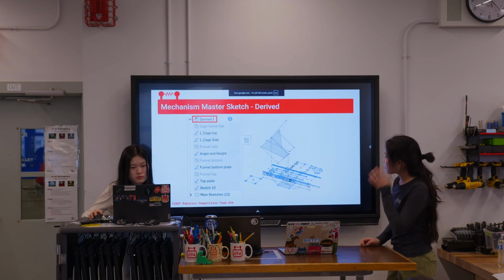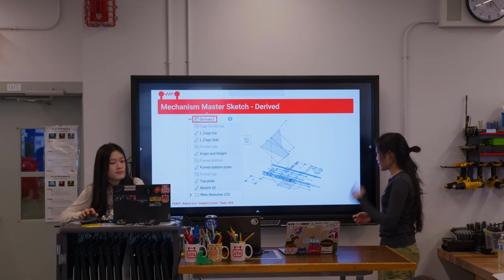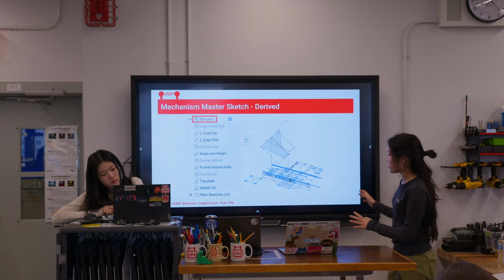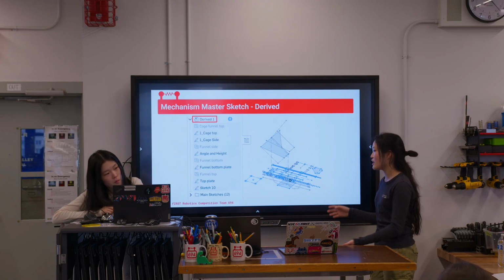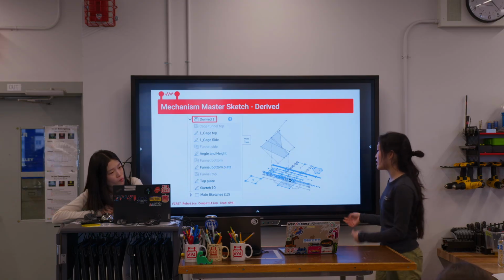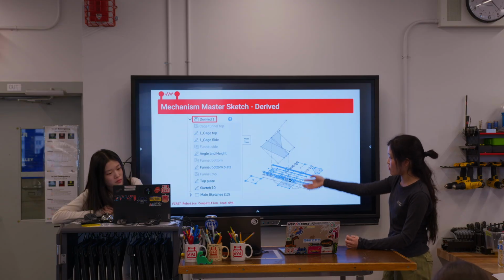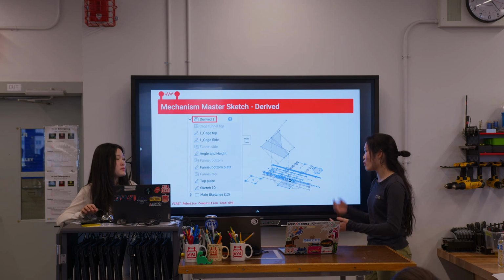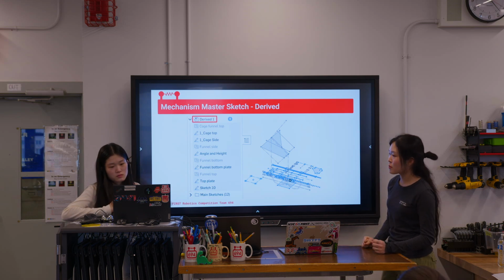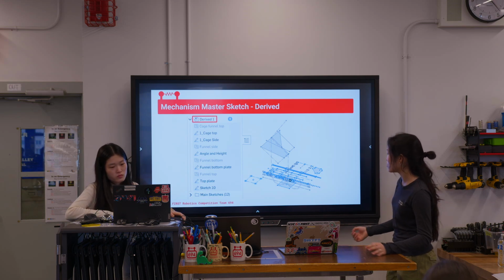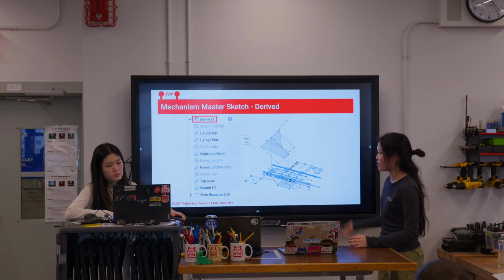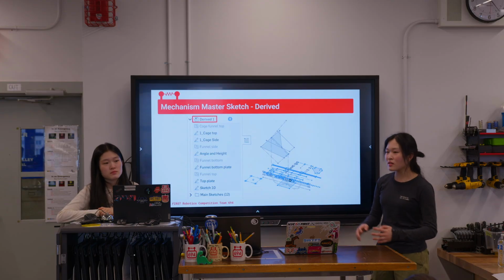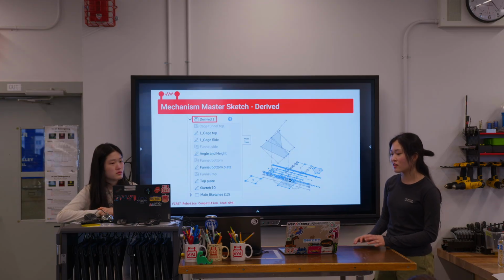Okay, so what I noticed, with a lot of people on our team not knowing, is a tool called Derive. What I saw that we're doing is, if you have a part and you need that part, they export it and re-import it into the document, but you have a tool called Derive, which lets you import sketches, parts, and some features from a different document, or even the same document, into another part studio. So in this example, when you create a mechanism, you'll be in a whole new document other than the main robot.